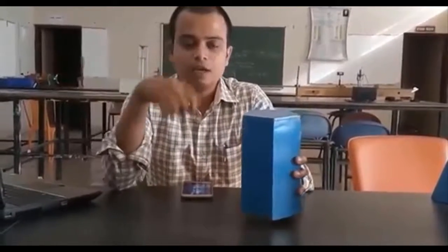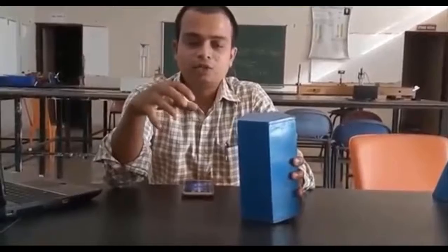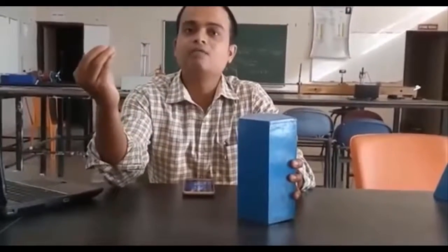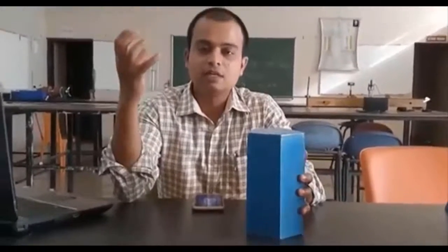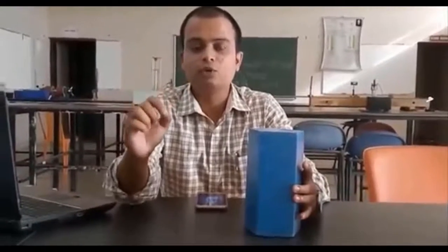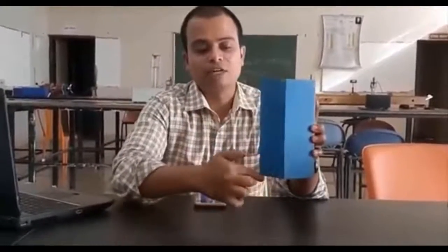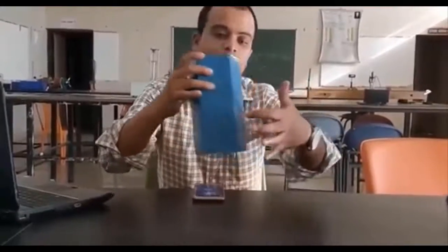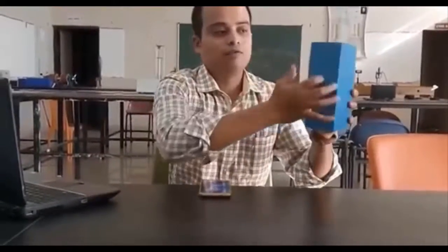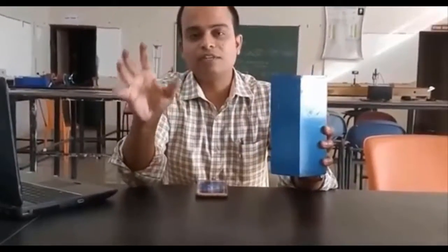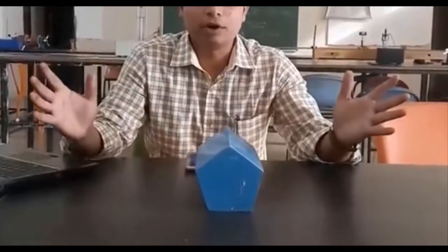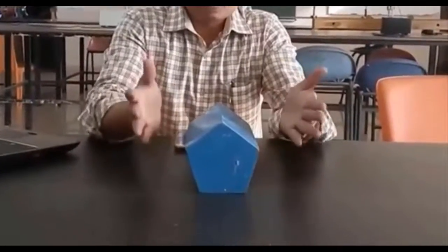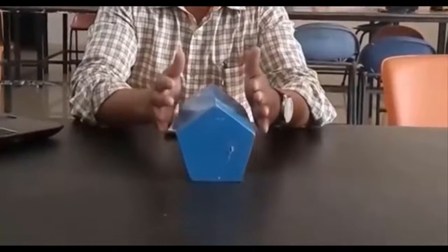50 millimeters. Now, we have been asked to solve this problem by ensuring that the axis makes a certain angle with the vertical plane, and that certain angle has been given as 45 degrees. So what needs to be done is, there are certain conditions which are to be followed. The first condition is that we've got to ensure that one of its rectangular faces. Now guys, you can see there are as many as 5 rectangular faces, 1, 2, 3, 4 and 5. Out of these 5 rectangular faces, we need to ensure that one of those rectangular faces remains in absolute contact with the horizontal plane.